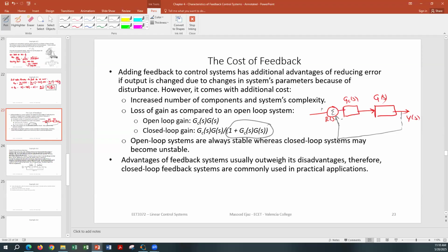Either it will be marginally stable, that is, marginally stable systems are ones where the system may become stable or unstable based on what type of input you're using. And again, that discussion is in the future. A stable system, for any stable input, the output will always be stable. An unstable system, even if your input is stable, the output is going to become unstable. Of course, if your input is unstable, then your output will be unstable, irrespective of whether your system is stable or unstable. So we don't give unstable input.